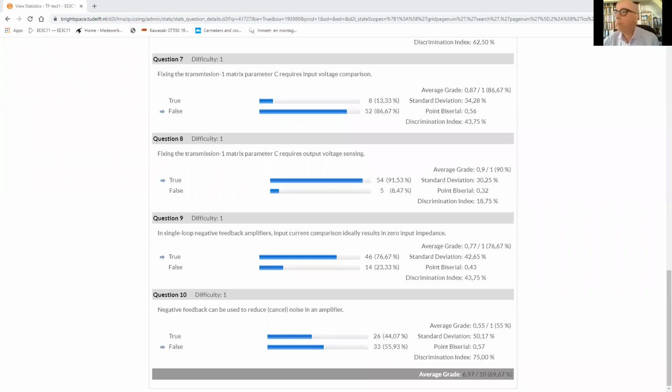So if we are at the input of the nullator subtracting two currents, and there will be no current flowing into your nullator, then all the current will flow into your feedback network and the voltage will be zero. So you have zero voltage and a finite current, which means zero input impedance. Just try to draw it yourself for a current amplifier.